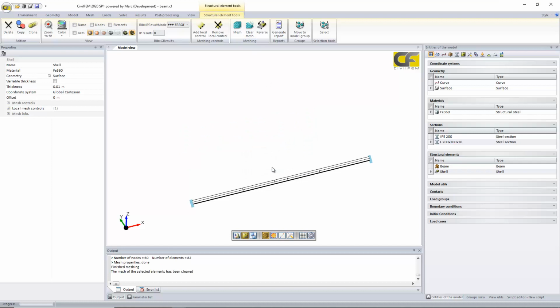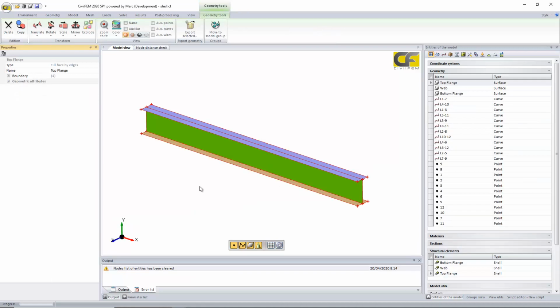How to interconnect two structural elements? If we want to obtain a congruent mesh, what are the options to interconnect the mesh between the nodes which are in common of structural elements which are adjacent? We can check that in a new example. If you had performed the example of the shell buckling, this is a very easy geometry.